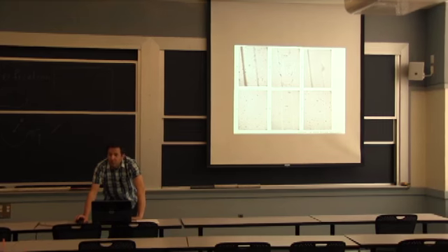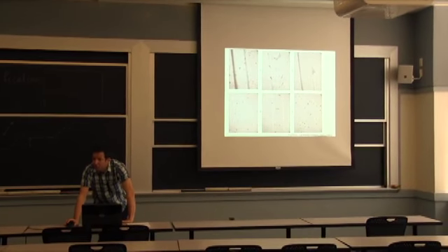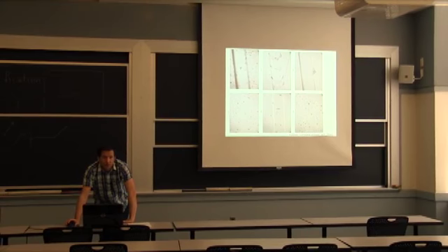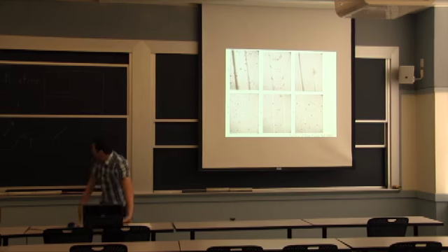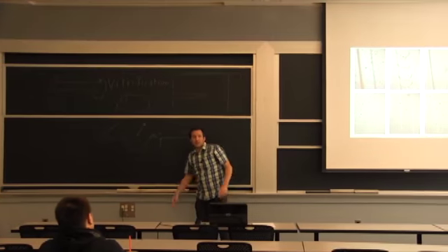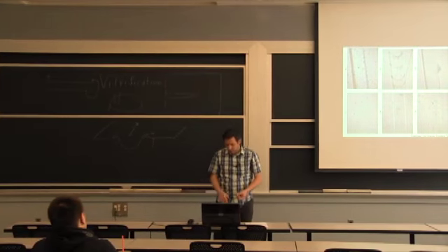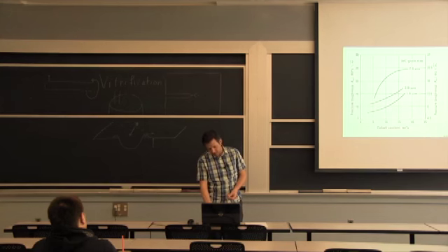This will be very easy to remove in a subsequent step, or even by erosion now at this point, because it's protruding from the surface. So all these materials, you can tailor your fraction of particle, the size, depending on what you're really looking for. Are you hoping to not lose weight during the wear? Or there are situations where you know that no matter how hard you try, you will be sometime forming these scratches, and you'll have material removal. It's something to think about.